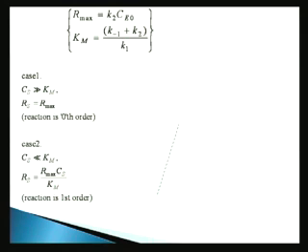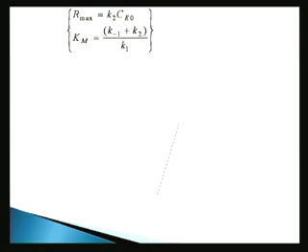What we'll do is look at how to evaluate these constants. So R max and Km are now my two constants. What have I been able to achieve by recasting it in the Michaelis-Menten form? Can you tell me that? Michaelis-Menten derived the form, good for them, but I don't necessarily have to recast my equations in that form. Why would I be motivated to do that? What do I gain by doing that?